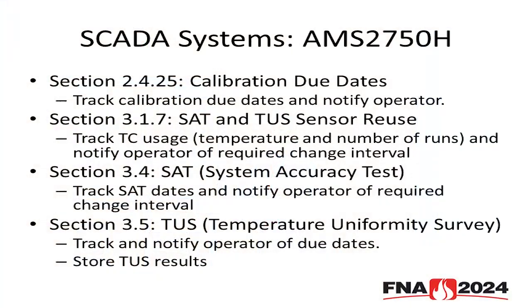So for example, calibration due dates and SATs and TUSs, temperature uniformity surveys, your due dates and your results of all of that can be saved in your SCADA system. So an auditor comes in and says, show me the last time you did all this. And you just go to the SCADA, and it's all right there. I can see when I did all these things. I can see the results. All of the results are in a CSV unalterable format, which is compliant, and you're going to be good to go.